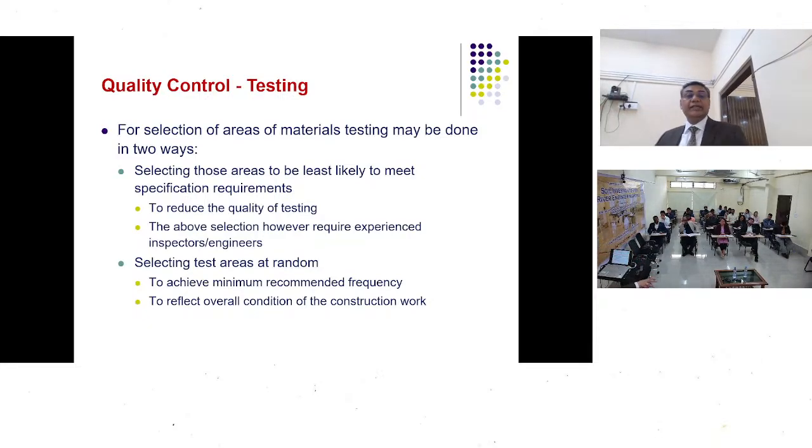So you have to select those areas. You have to reduce the quantity of testing. The above selection, however, requires experienced inspectors or engineers. As I was saying, when you go time and again, you are able to identify, okay, this area I have to look at, this I have to look at.